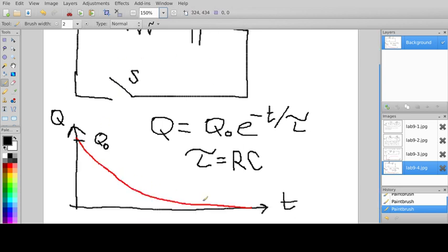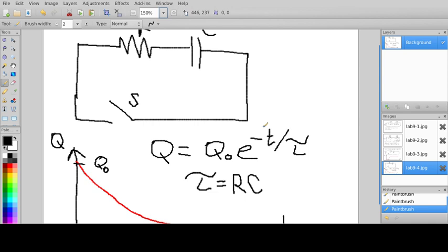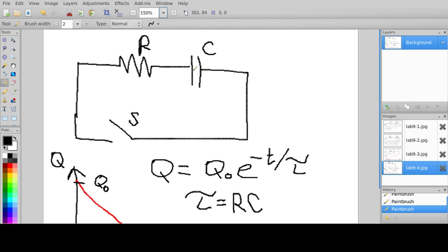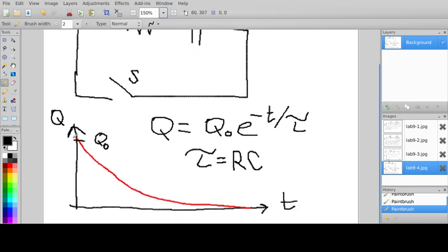And as the voltage decays, you would have put your oscilloscope in this special mode called triggering, okay? And what triggering does is basically, as the voltage decreases past a certain point, that's when it's displayed on the oscilloscope. Otherwise, the oscilloscope would just be displaying some constant voltage across that capacitor forever and ever. And then you short it, and suddenly it would go to zero, and you go, well, I didn't see it happen because it would happen in real time. So basically, when you put an oscilloscope in triggering mode, it captures that moment when the voltage drops below a certain amount.